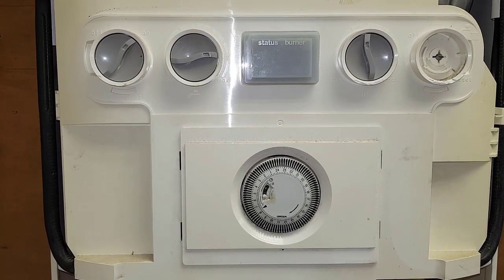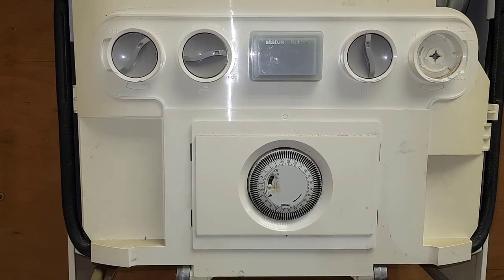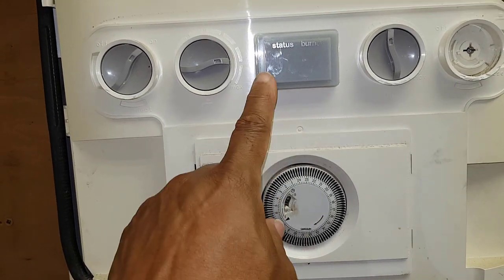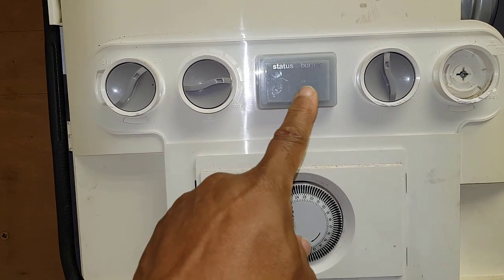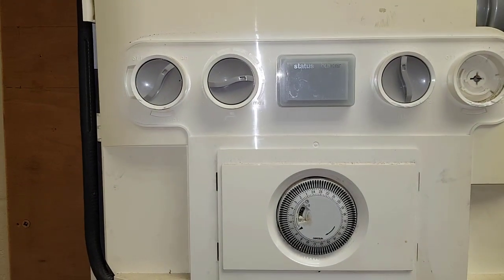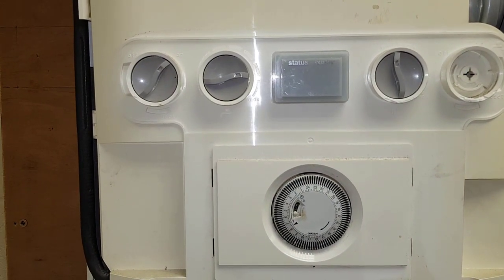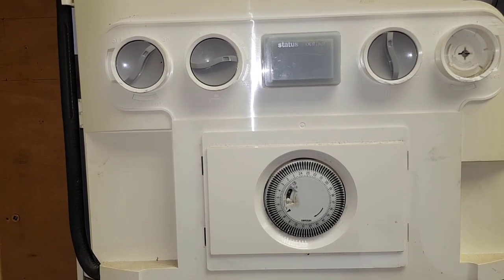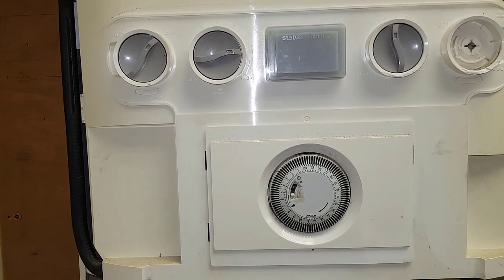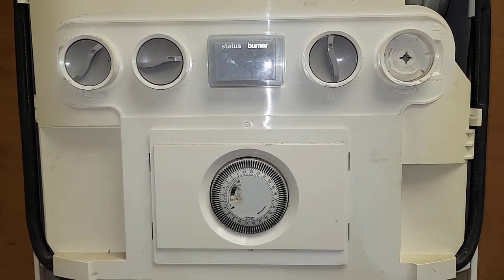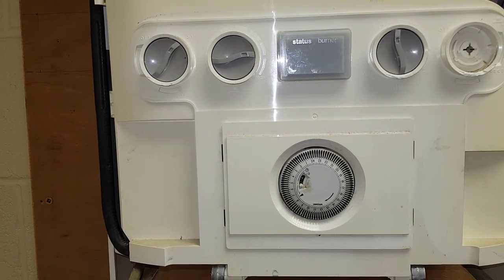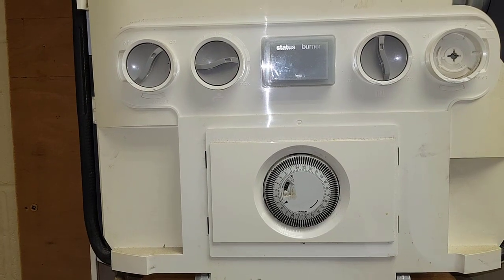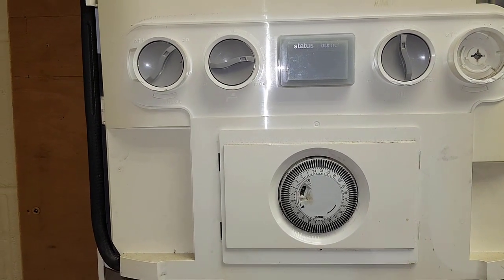They call you out. A symptom for that would be you turn on the room thermostat, C comes on, no problem. The burner light comes on, fires up. But after about a minute it goes off. Then it might repeat that after two or three minutes and keep doing that. Other guys who might not be as knowledgeable could dive in, get too deep and overlook something really simple.